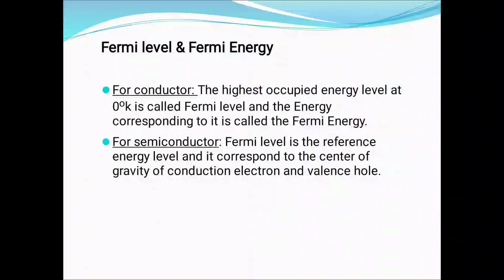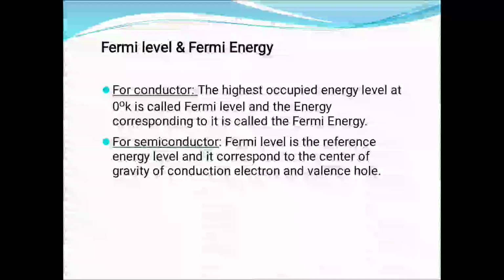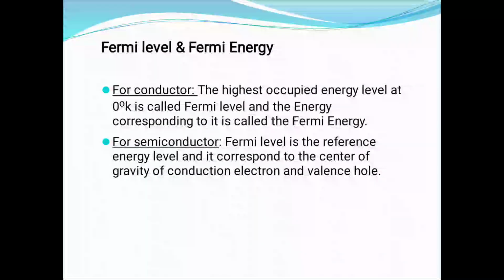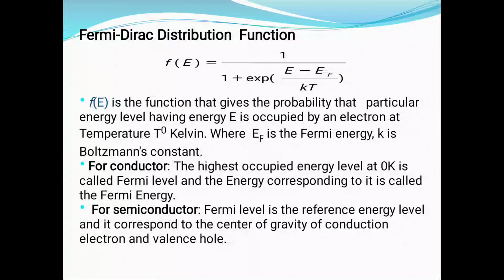For conductors, the highest occupied energy level at 0 Kelvin, absolute temperature, is called the Fermi level, and the energy corresponding to it is called the Fermi energy. For a semiconductor, the Fermi level is the reference energy level and it corresponds to the center of gravity of conduction electrons and valence holes. Fermi-Dirac function.